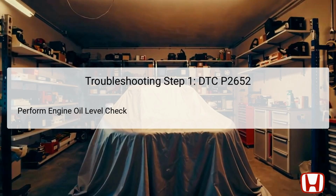The first step in troubleshooting DTC P2652 is to perform an engine oil level check. Ensuring that the engine oil is at the proper level is critical, as low oil can affect pressure readings and overall engine performance. To check the oil level, park the car on a level surface, turn off the engine, and allow it to sit for a few minutes.